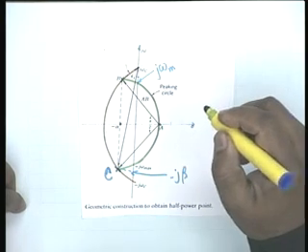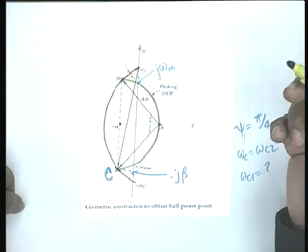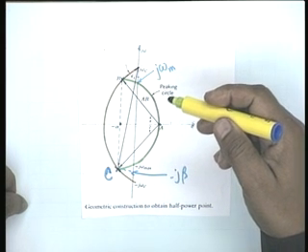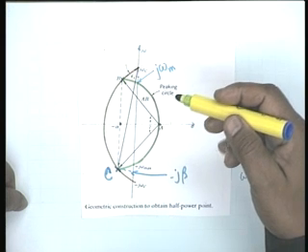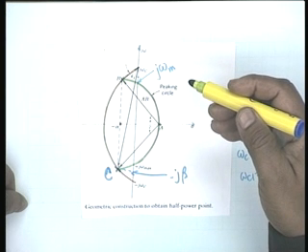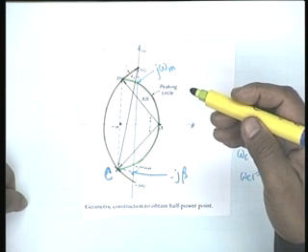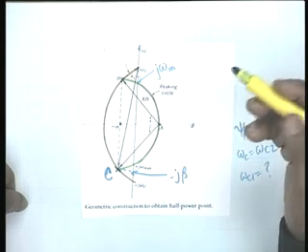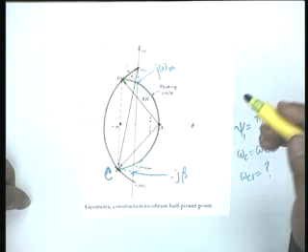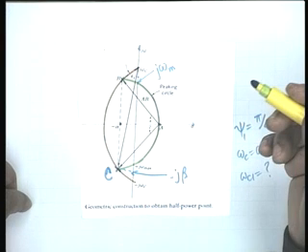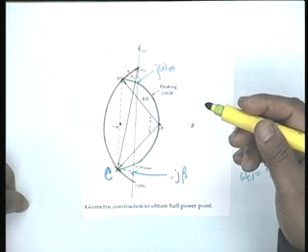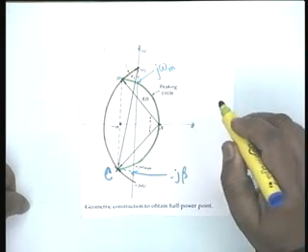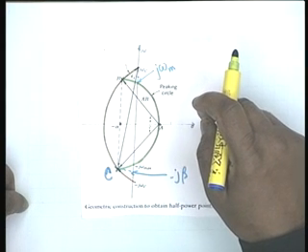Omega c1, as we know, may or may not exist. Omega c1 will not exist if the maximum is less than how much? Now root 2, if the DC value is 1, if the maximum is less than root 2, then omega c1 does not exist, and that is one of the reasons why a geometrical construction like this does not disclose omega c1, it only discloses omega c2.